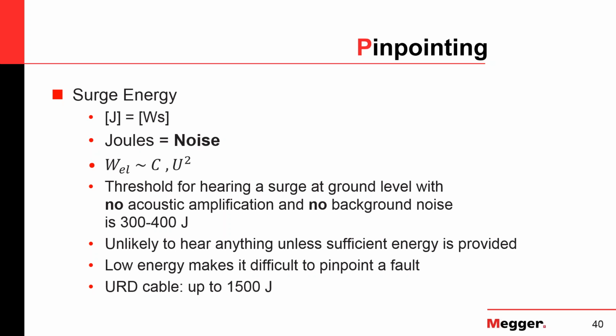So you have choices. And one very practical choice, always thump at the lowest possible voltage to get the maximum energy out of it. Of course, you still have to make it flash over, and if you are above the rating of one of the stages, well, then you can't help it. But if you have a multi-stage thumper, let's say 8 kV and 16 kV, and it flashes over at 7, be in the 8 kV stage to actually utilize more energy. Don't be in the 16 kV stage, because 7 is even less than half of 16, so you will drastically diminish the energy you can pump into the fault to create noise.